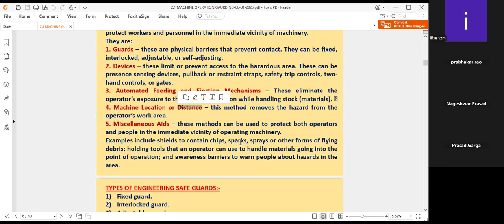They have to remove all the dust accumulated on the impellers, the motor body, the pump body, and in the pipelines, as well as remove the guard and see that there is no accumulation of liquor or liquor mud.